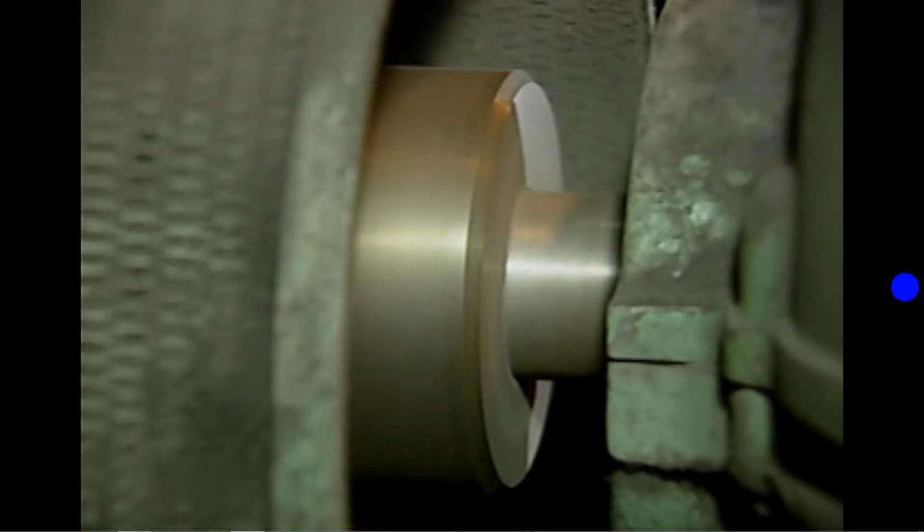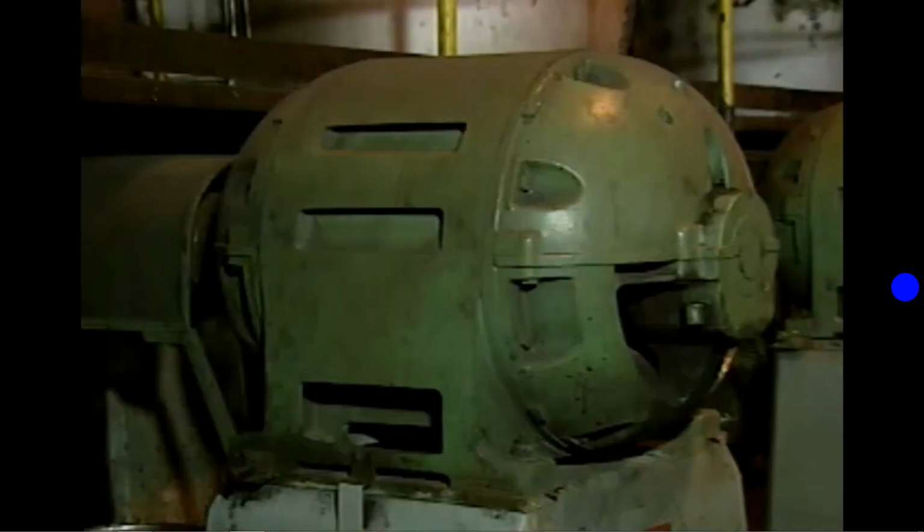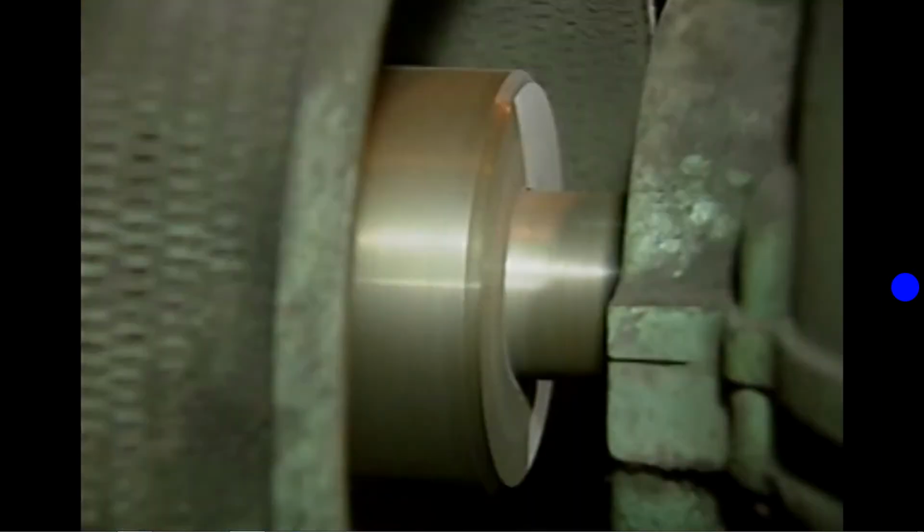operating properly. For example, a motor that is operating correctly should have a smooth, steady sound. By carefully listening to an operating motor, you may be able to detect an unsteady sound or an increase in motor noise that could be an indication of a problem, such as an electrical fault or bearing failure. Unusual movement of the shaft or vibration of the motor can also be an indication of a problem.